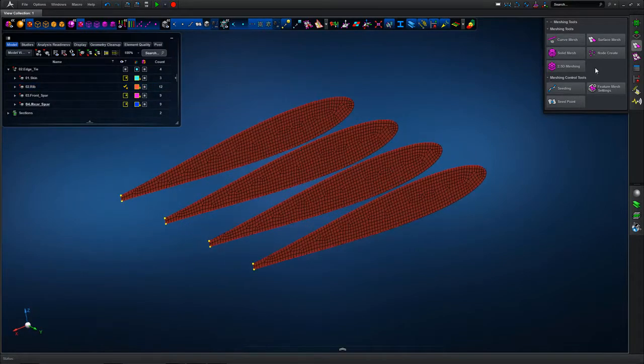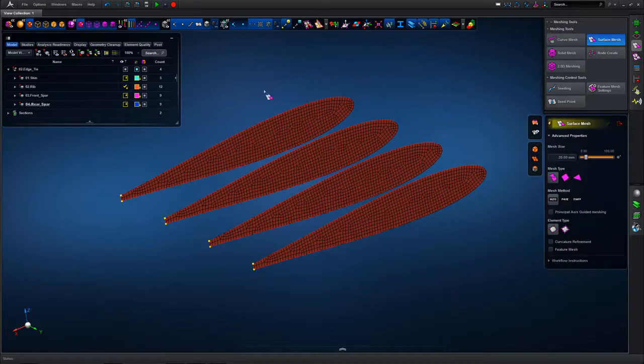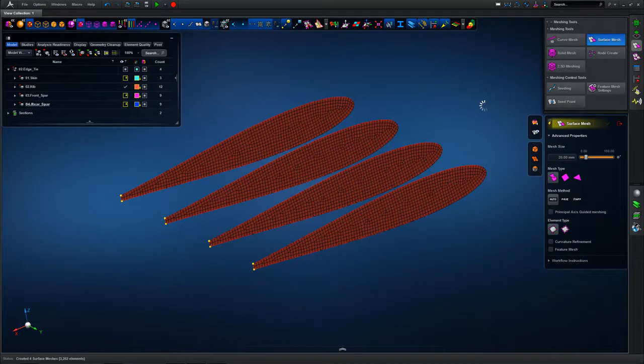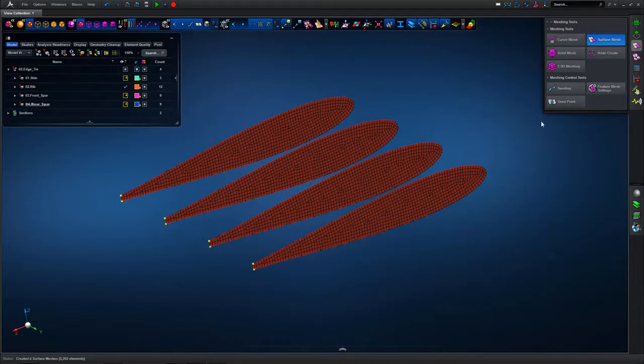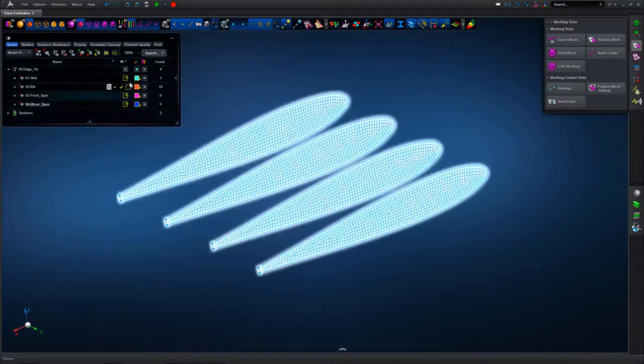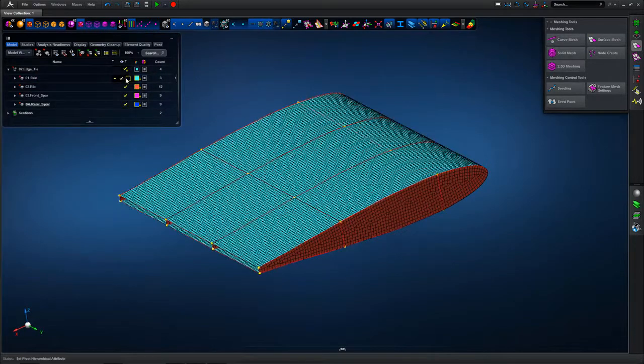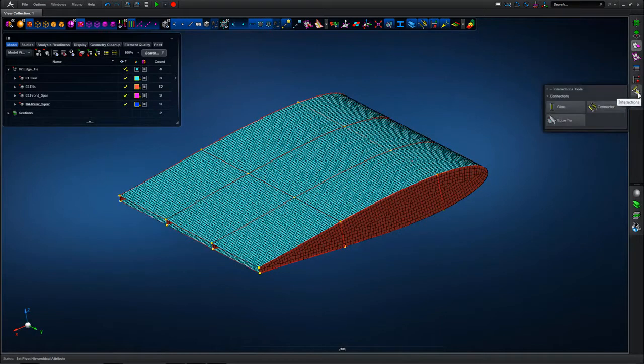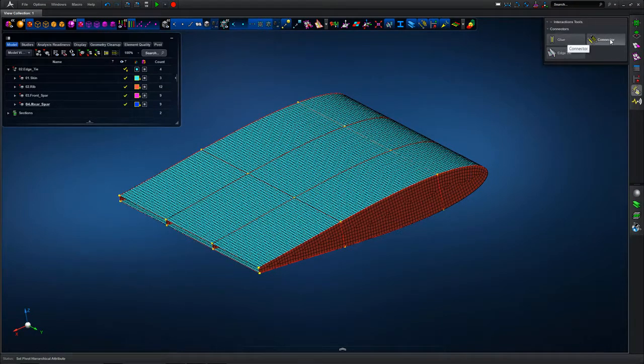So I think we're going to just look at some of the local change here. So we're using the hybrid quad tri mesh for the ribs, given the slightly irregular shape, but the rest of the structure is quad meshed based on the simple surface geometry.